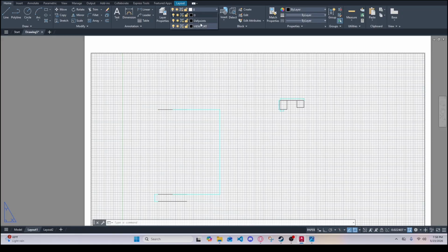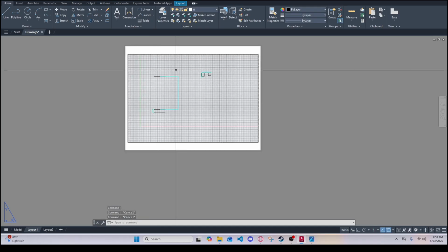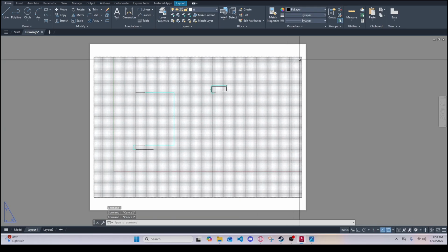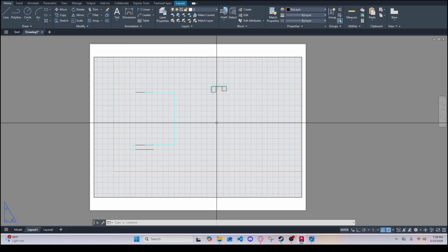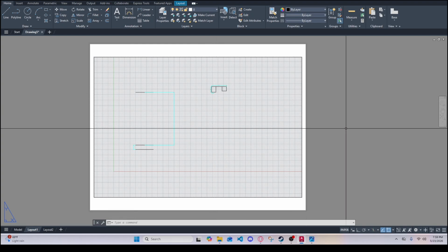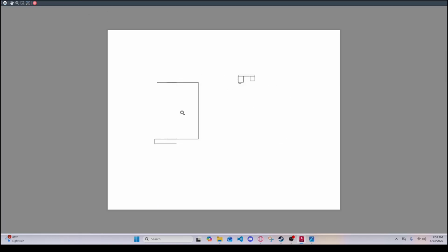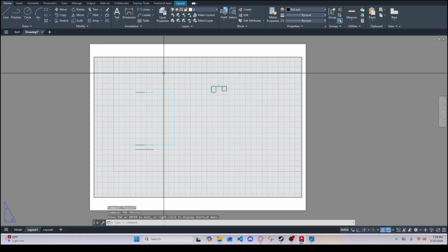Because right here you can customize it to say you want it to be steel, you're working with steel, plastics, concrete, whatever. It's very customizable, and you can change different colors. But again, let's go ahead and click into our viewport, because now, as you can see, it's not a thick line either, and it's not going to show up once we click print. And you can also see it if you type in PRE for preview. So now the only thing that's showing is what we had before.